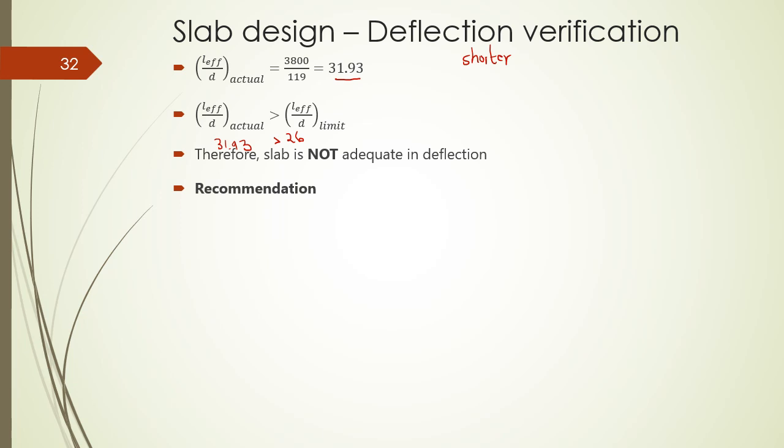When this happens, we note our slab has failed our serviceability limit, and we can recommend that we increase the slab depth or increase the tension reinforcement.